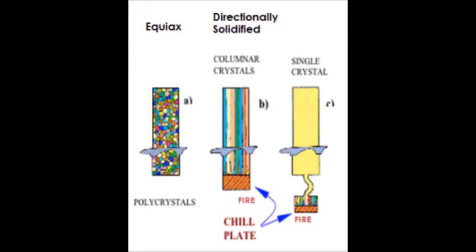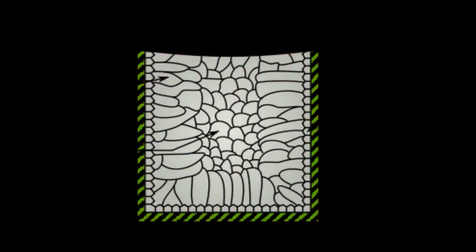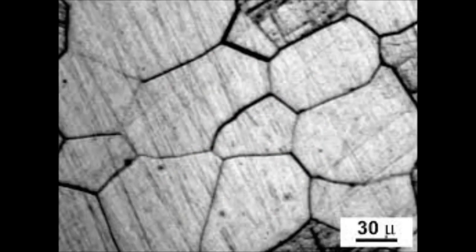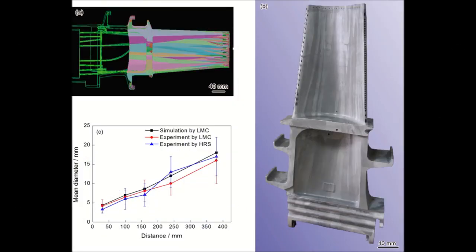There have been 3 different ways to manufacture an engine turbine blade with the HIP: equiaxed casting, directional solidification, or DS, and single crystal, or SC. Equiaxed castings are crystals that have axes of approximately the same length without any order. This type of casting creates grain boundaries or defects in the material and can form failure points. Due to these failures, turbine blades began being manufactured with DS.